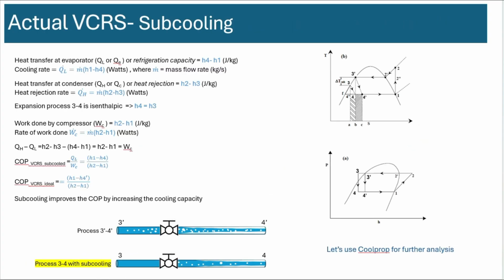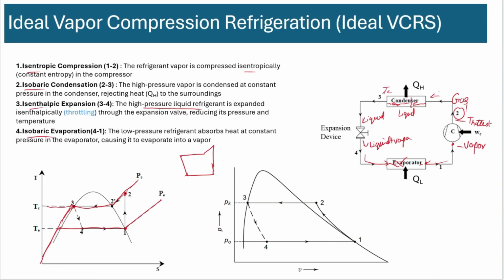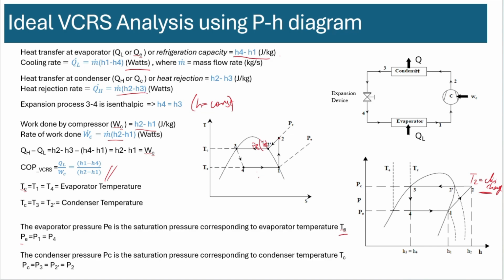Now, in a real vapor compression cycle, okay, these are ideal. Why are they ideal? There are several reasons. One of them is the processes involved are ideal processes. You have isentropic compression, you have isenthalpic expansion, all that. Those are not real. Even the constant pressure process is not real. You have some pressure drop here, some pressure drop here too.